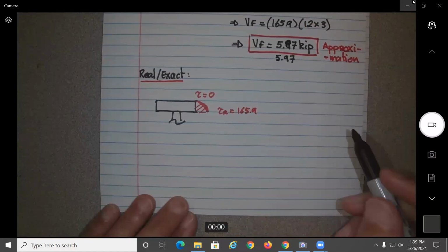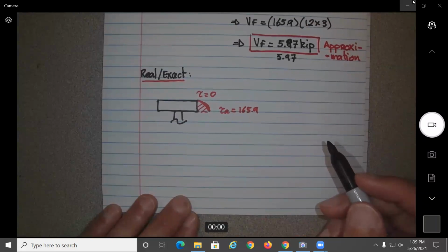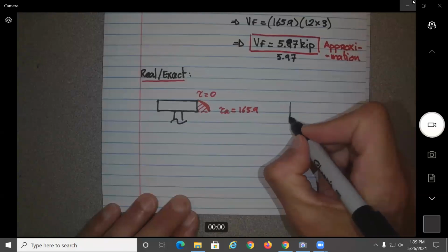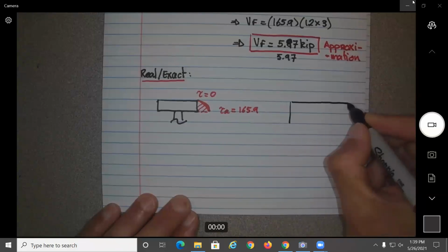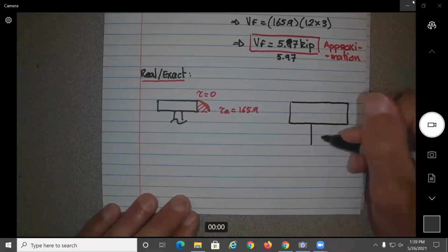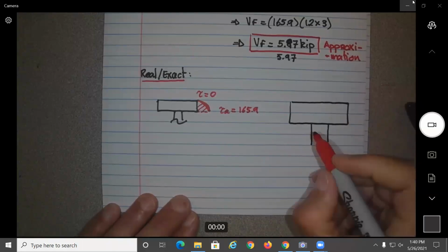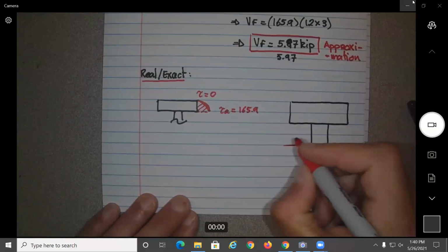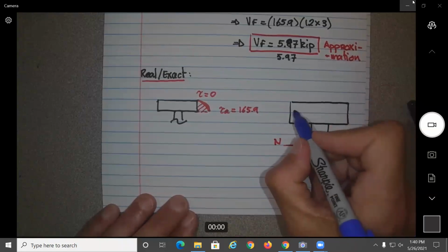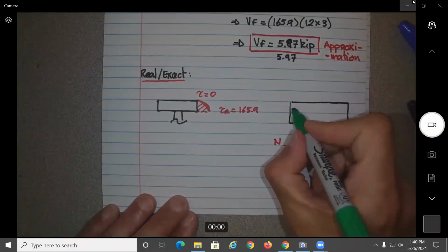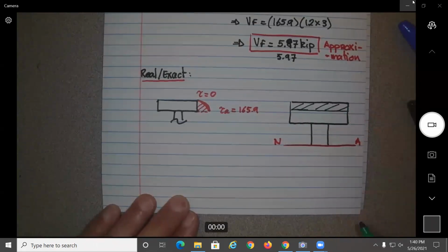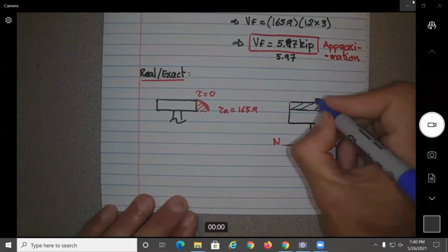So I need to redo the figure over here. Did I go to the next page? No, probably I can do it here. Just try to go a little bit bigger. So this is our top flange. Here I'm just going to do up to the neutral axis. All right. So this time, instead of taking the whole area, I'm just going to take a piece of the little area here. We know this will be 12.